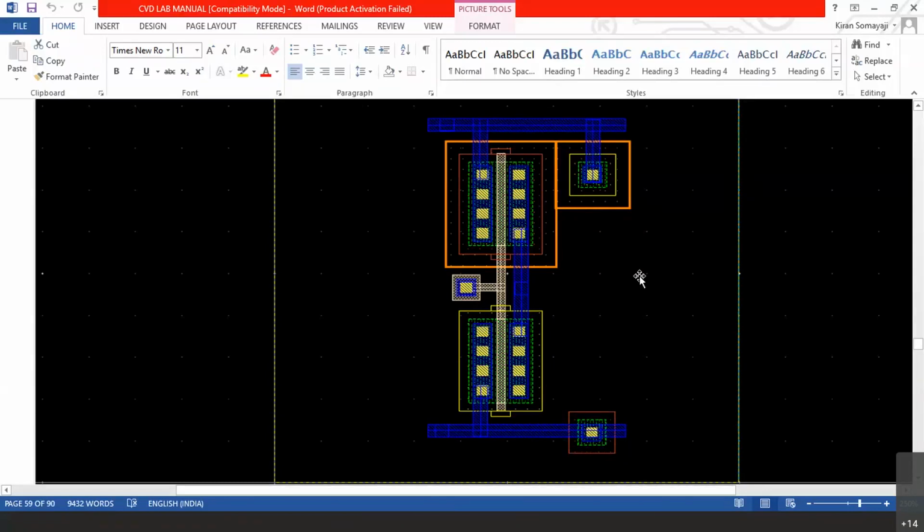So, even though in the circuit diagram we write VDD at the top and ground at the bottom, as per our writing style or writing habit, now in the layout you may again think ground is at the bottom and supply is at the top. No, not that way. This blue layer is always the topmost layer.